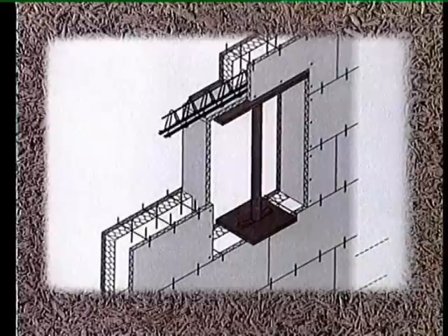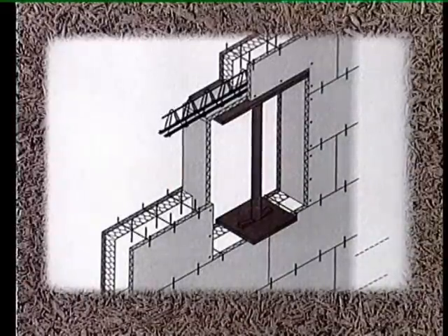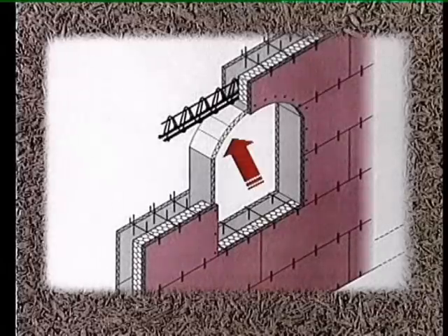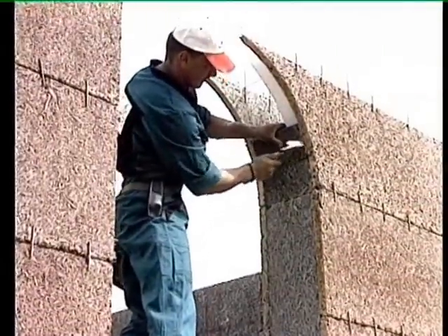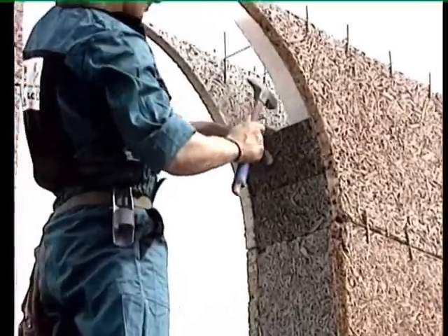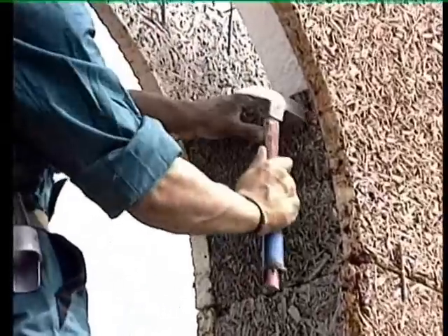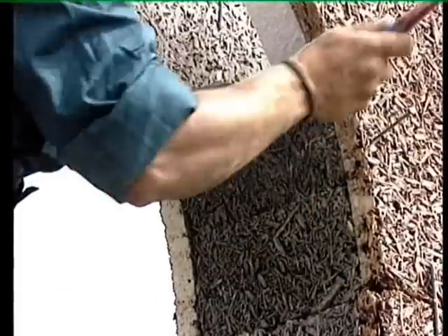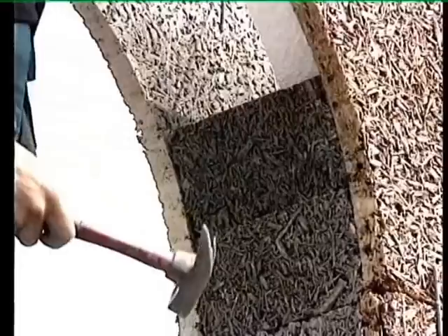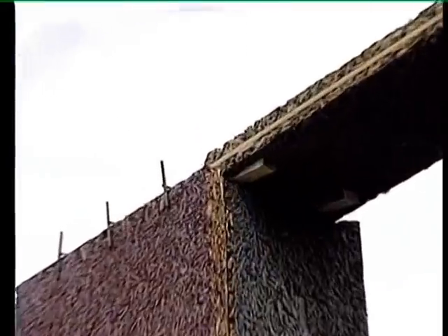After the concrete hardens, we continue with the construction. Reveals for window frames are built and boarding for lintels is also assembled. Door openings are created in the same manner. Staircase or lift shaft assembly is performed at the same time. We continue in the same manner up to the lower level of the ceilings.